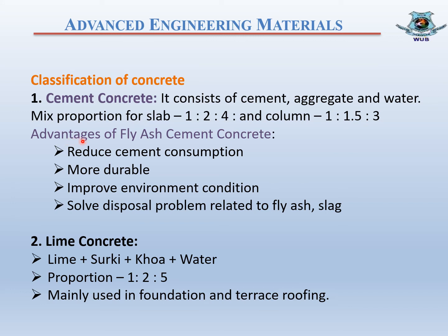Now, advantages of fly ash cement concrete. If we use fly ash, it will reduce cement consumption. It is more durable than ordinary cement. It improves environmental condition and it solves disposal problems related to fly ash and slag, as these are used in fly ash concrete.